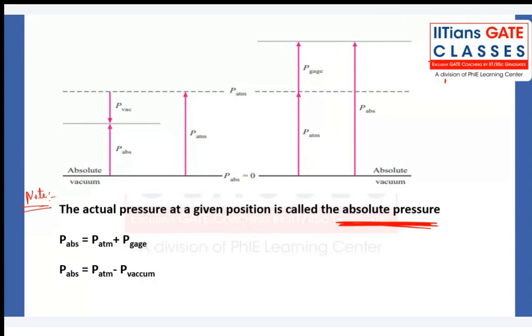That is the starting of the statement. The pressure is same in all the directions. But remember that the Pascal law is applicable even though the fluid is undergoing motion. That is a rigid body motion. Even though it has the acceleration, still we talk about the validity of the Pascal law. How and why? Let's discuss that in detail while discussing this particular slide.